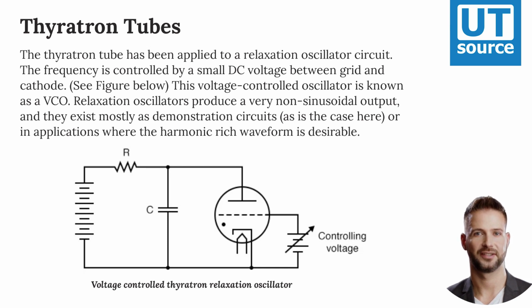Load voltage exists, and thus load current, even when the AC voltage waveform has dropped below the threshold value of the tube. This is hysteresis at work. The tube stays in its conductive mode past the point where it first turned on, continuing to conduct until the supply voltage drops off to almost 0 volts.